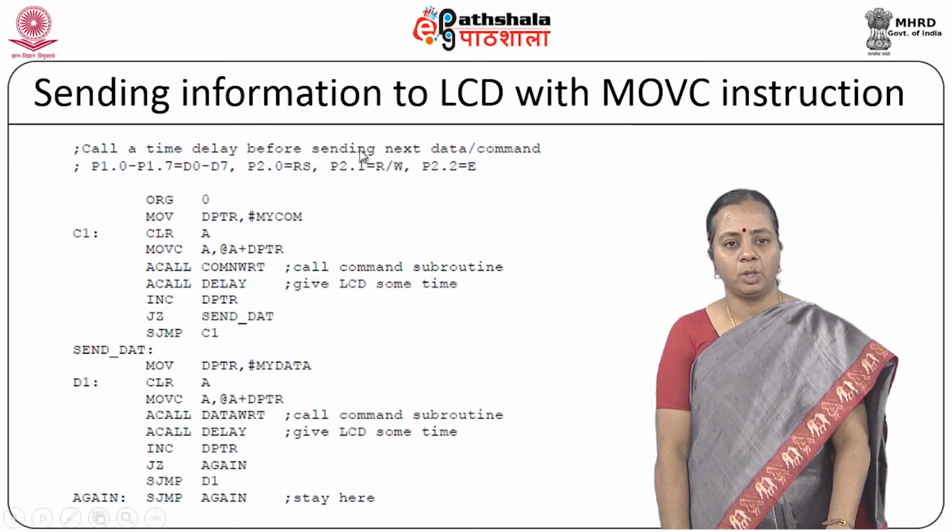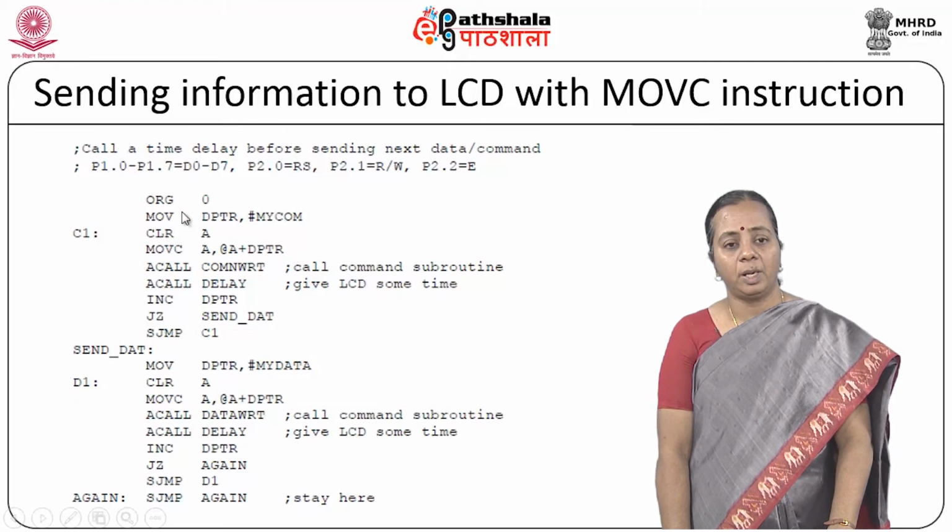So when you are looking at this, there is no need to take the data from the hard coded things. You can read it from a different location. From there onwards you can move the data and you can write it in your LCD. That also can be done. This has been demonstrated with this particular code segment, where MOV DPTR, #MYCOM.